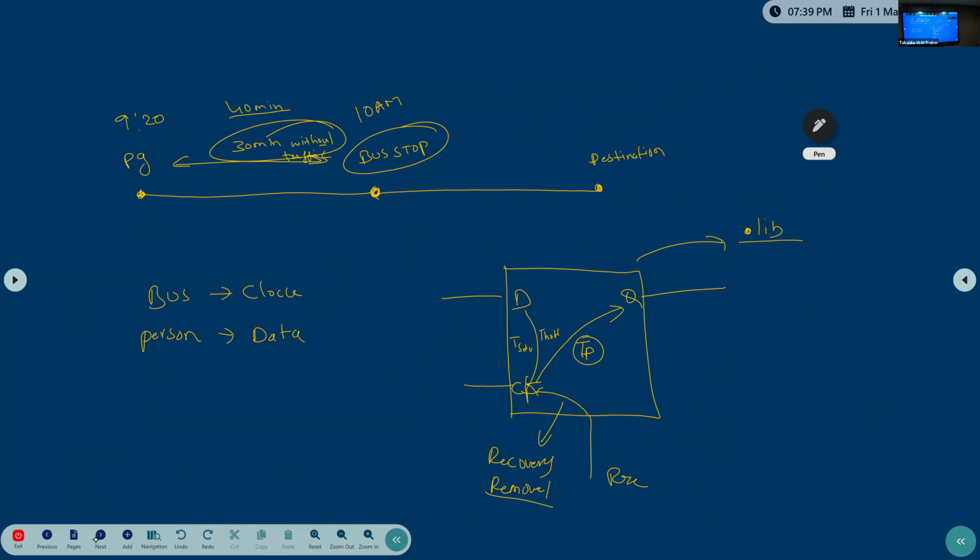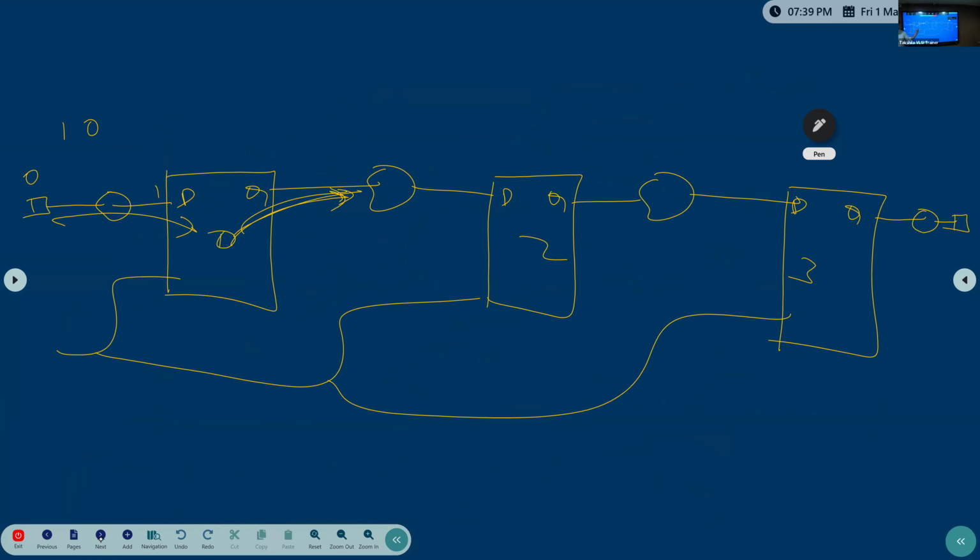The timings are whatever we discussed. They will ask between flop 1 and flop 2 timing: is the setup time met or not? Is the hold time met or not? They will ask, so by seeing the delays, you need to say everything.